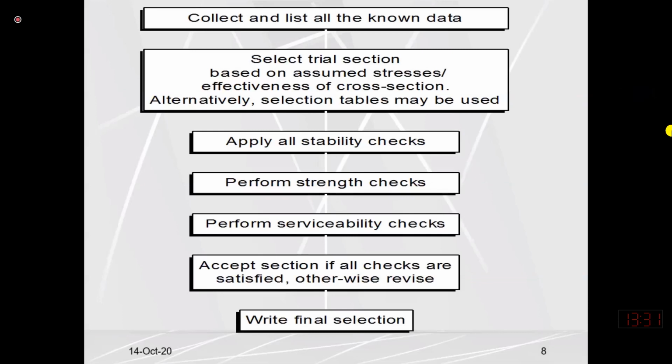But in this particular design class, just for our practice, we have standard sections. Standard sections mean sections which are manufactured as per AISC requirements. AISC says that if we have a section whose depth is equal to 300 millimeter, then for that section use a web thickness of 10 millimeter, a flange width of 300, and a flange thickness of 12 millimeter.